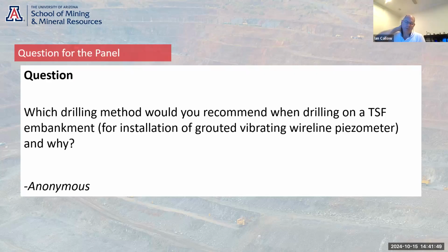Yeah, I mean, if it's a rock dam, and you assume you're putting the piezometer in a drainage blanket or something like that, you won't get any return of your grout. So you just need to be aware of how the holes get cased above a drainage blanket or a filter that you're trying to monitor. Yeah. So be aware of that. You certainly won't get any return through a rock fill dam.